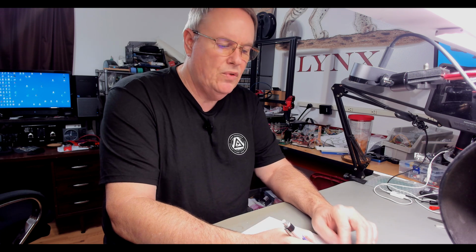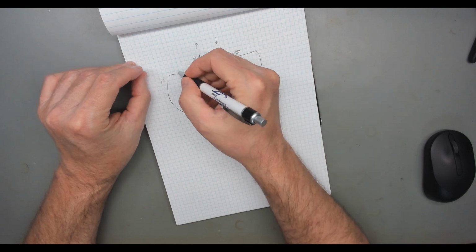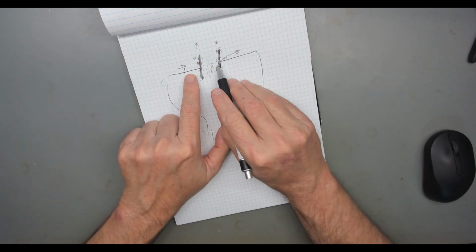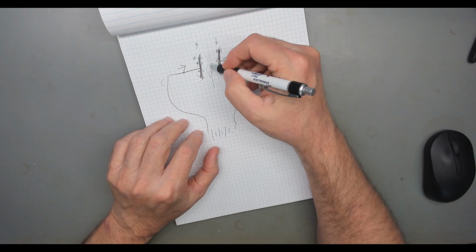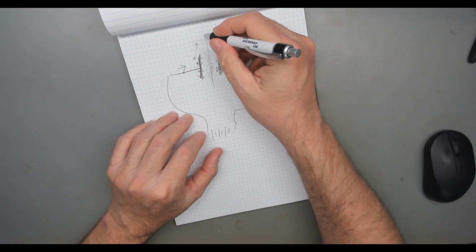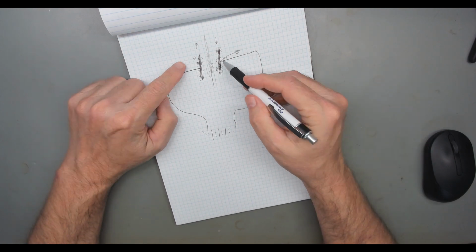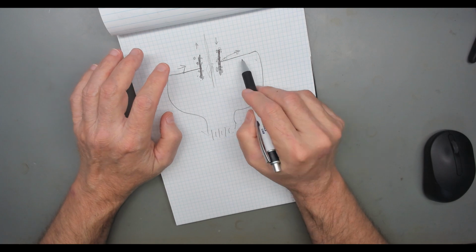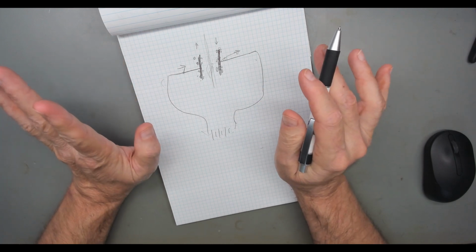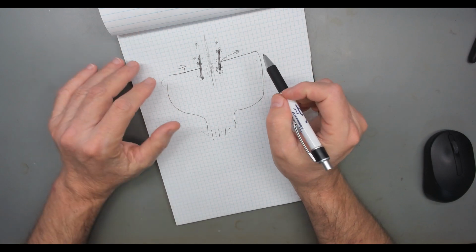But current does flow in a circuit with a capacitor when you first apply it, because these electrons move this way. They move this way. Because of that, current flows in the circuit. But technically speaking, other than leakage current, current doesn't flow from one plate to the other. So we hook up a battery and we see current appear to flow through this capacitor at first. But we're really just draining one side and packing it on the other side.